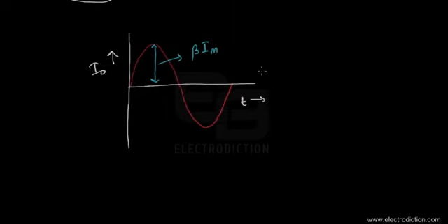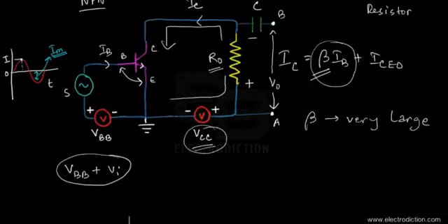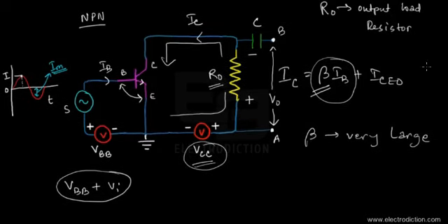much like this particular waveform as you can see over here. Now, how did this happen? What did the capacitor do? Okay, let's once again refer to our diagram. Well, if you refer to the properties of the capacitor once more, then you'll understand why this happened. It's because capacitors don't let DC current or voltage components pass through themselves. What they do is let the AC components pass otherwise.